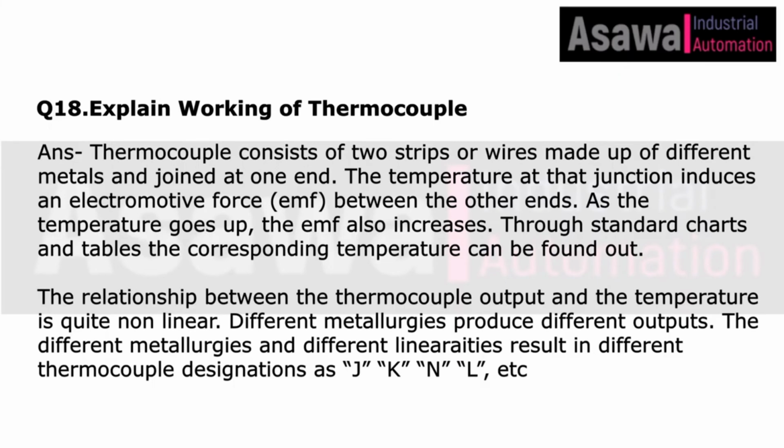The relationship between the thermocouple output and the temperature is quite non-linear. Different metallurgies produce different outputs. The different metallurgies and different linearities result in different thermocouple designations such as J, K, N, L, etc.